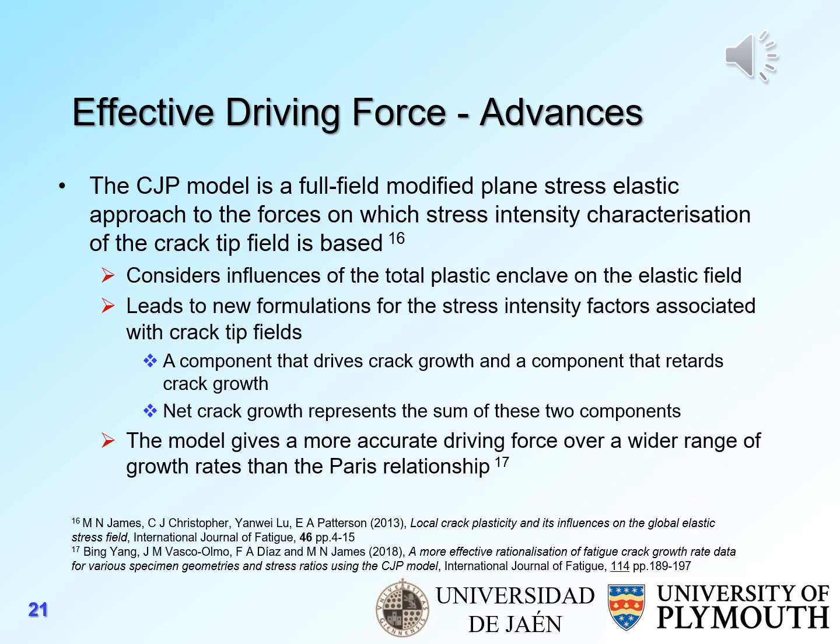In my own work, after many years of studying fatigue crack closure in the light of what Riemelmoser and Pippan and Sadananda and Vasudevan had said in their work, I ended up proposing the CJP model with colleagues Colin Christopher and Ian Patterson. And that is a full field modified plane stress elastic approach to the forces on which stress intensity characterization of the crack tip field is based. And what I hope it does a little bit better is consider the influences of the total plastic enclave on the elastic field that drives crack growth. What it does, that's somewhat controversial perhaps, is leads to new formulations for stress intensity factors that are associated with the crack tip fields.